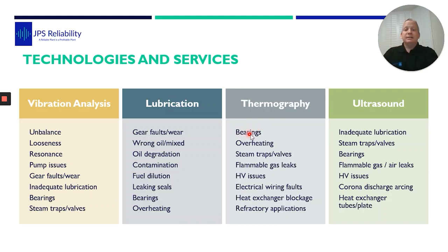Whereas by adding vibration analysis now, we can detect bearing faults, but we get it earlier. It gives them more lead time, they keep fewer spares on the shelf, and they can schedule it in without affecting production. And again, ultrasound would be gold in this area. Contact ultrasound will pick up those stress risers really well, and lubrication as well. If you did lubrication analysis, you would pick up the particles in the oil. This shows you all four must be used together to have a really good system.